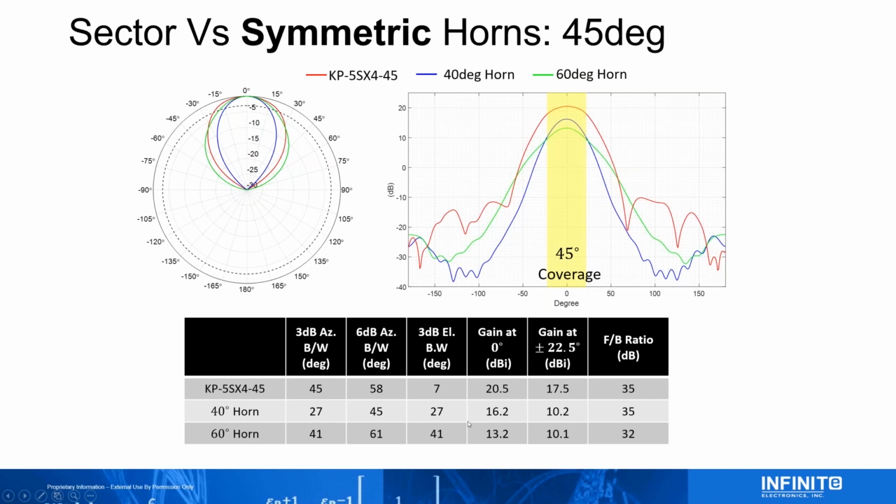So you just have to be very careful in how you're using these, because you're going to see a lot less signal strength if you pulled out a sector, thought it was the same beam width, and put up the horn. Even though it's smaller and gets a little bit less wind loading, you're going to have that issue where the gain's dropping. You might lose a few customers.